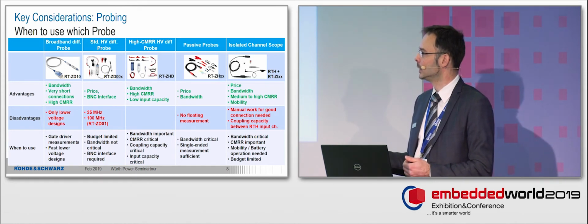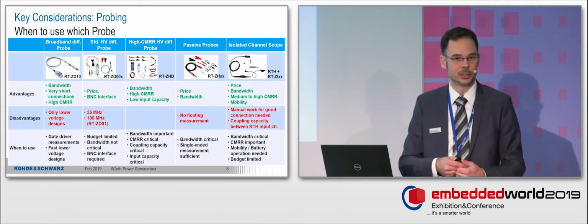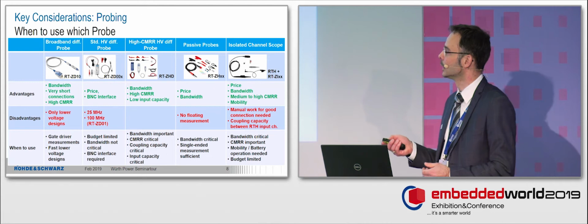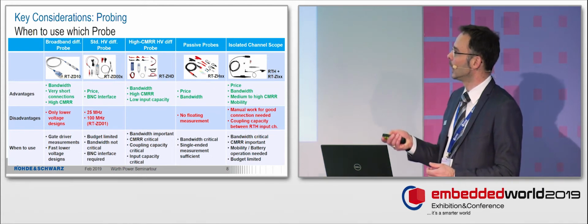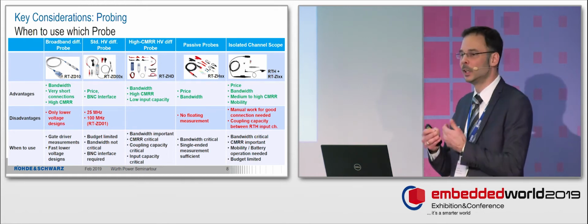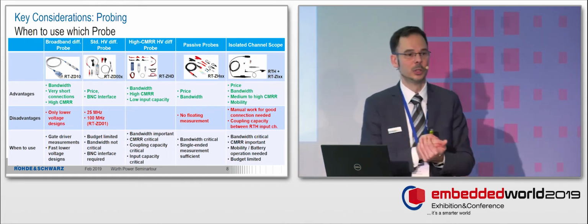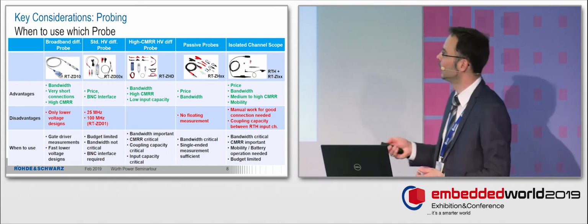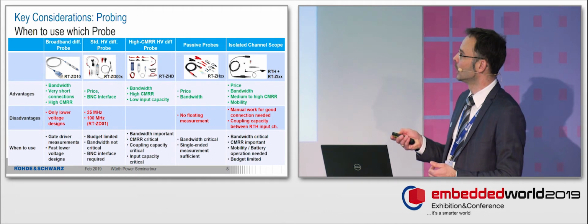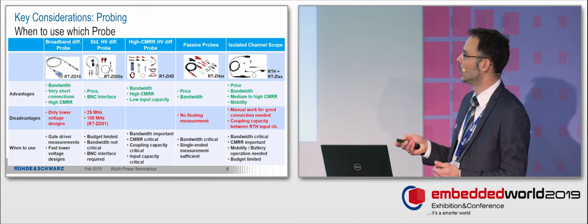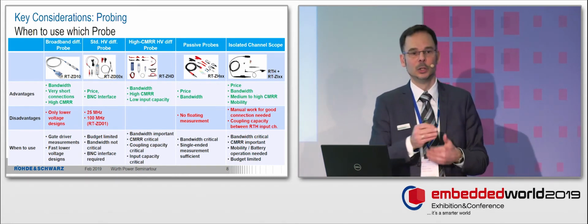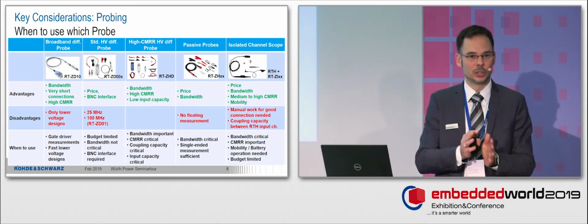So maybe that's something that's interesting for gate driver measurements or something like that, but not connected to a high voltage design at the end. This category I introduced here because you actually find different high voltage differential probing solutions in the market. And there's something that I would say is standard. When you look at those products, we also have such products in our portfolio, but they are not really designed for switching analysis. Usually bandwidth is not so high, so it's not the right choice.